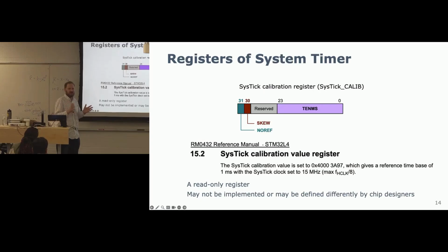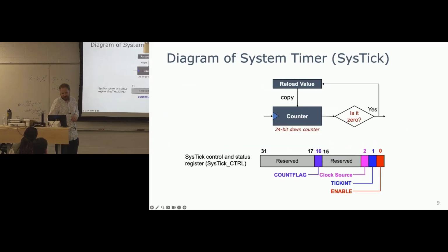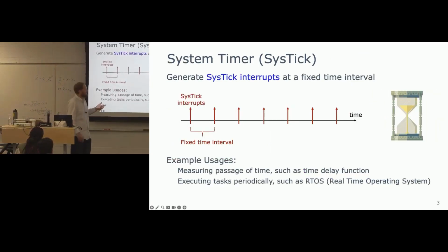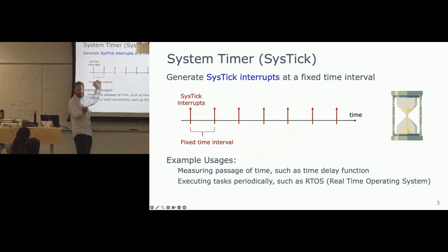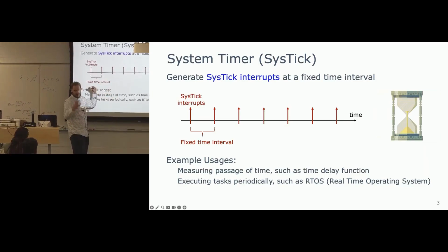This is where you will see frames and frame pointers in your code if you went through all the disassembly stuff. So yeah, it's just about controlling program execution. So if the program takes too long, you would halt that. If it takes too long, then you're going to halt execution. It depends how you set it up, but if your program takes longer than this to execute, then it will halt execution of that program and do a context switch to another program, which is essentially just, think about it like an interrupt. You're going to unstack the thing, put a new one on. Then you're going to go and do this other program, then go through your queue.